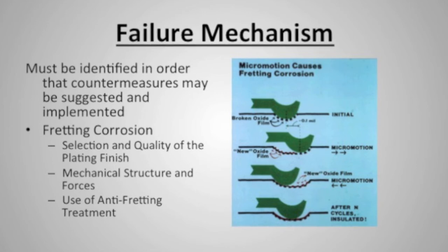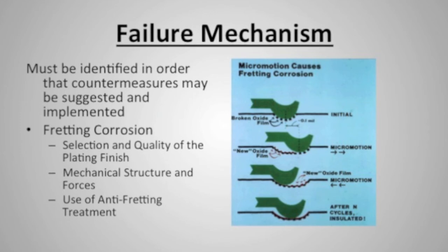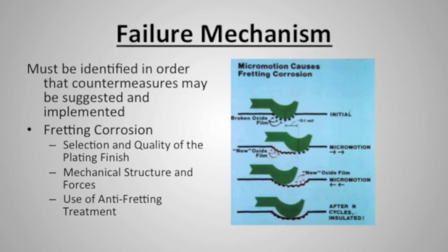Fretting failures are easily prevented by assuring adequate mechanical integrity, by properly specifying quality plated finishes, designing in enough normal force, and by using anti-fretting surface treatments.